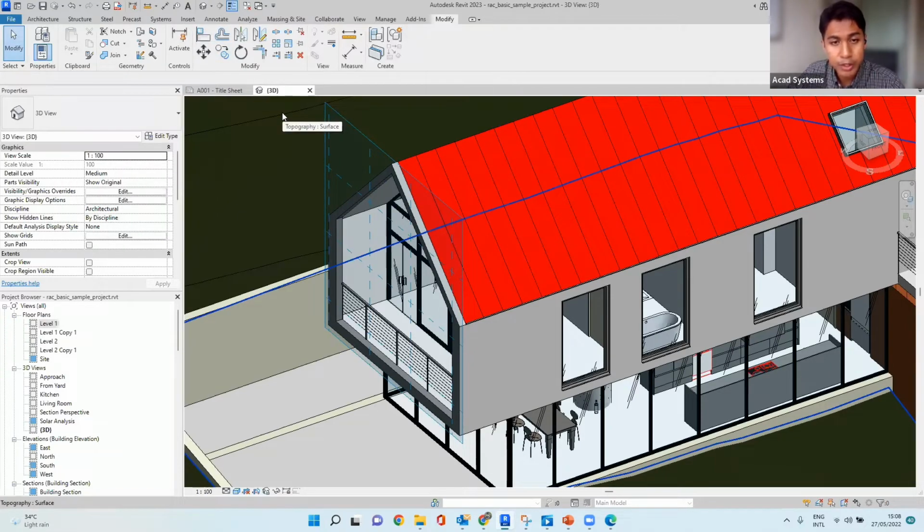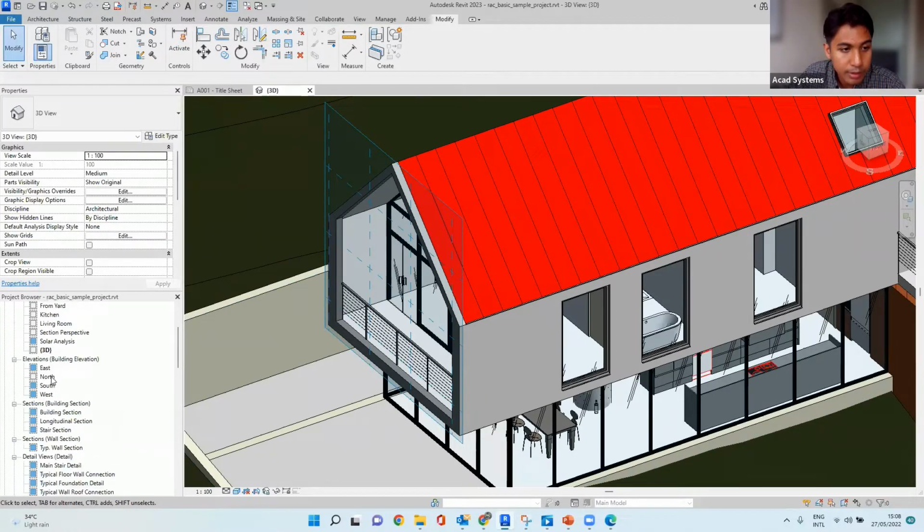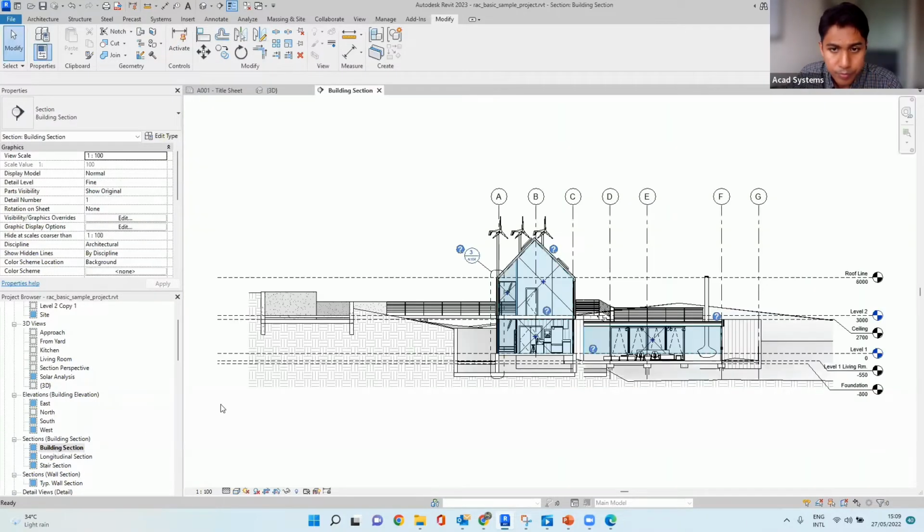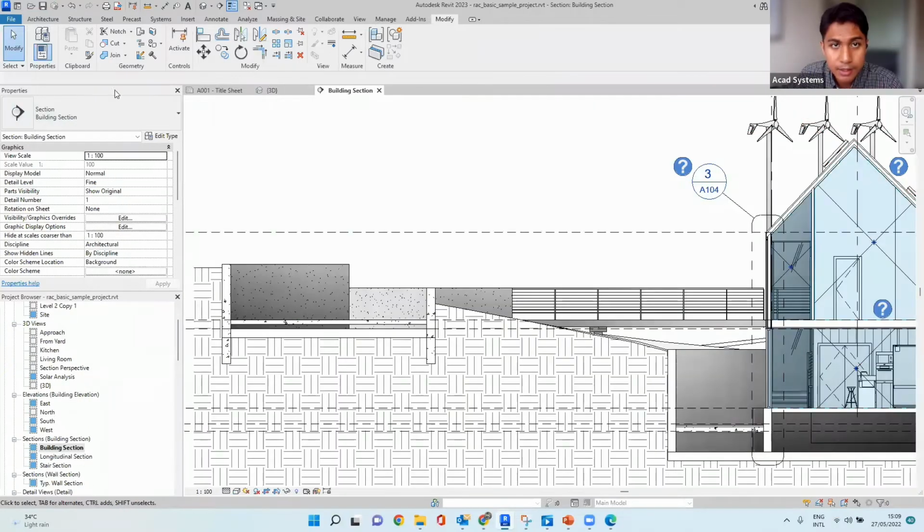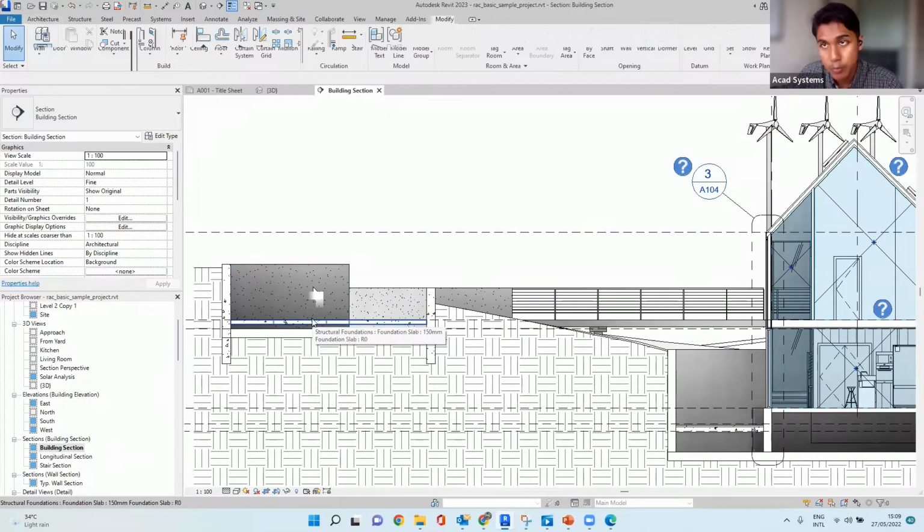Before we try to import, I would like to create a reference plane. Well, this kind of ties to the previous work plane. So this feature is kind of related to the one that I mentioned before. So for example, we go to a section view, and then I would like to place a car, for example. I'll be importing a CAD file for a car.